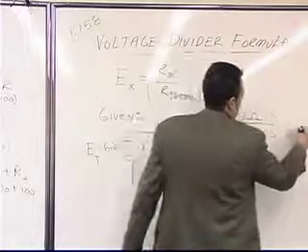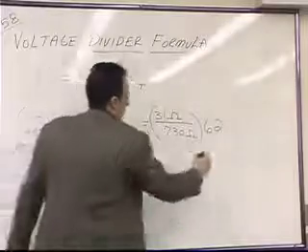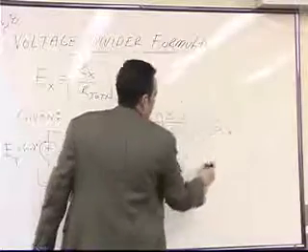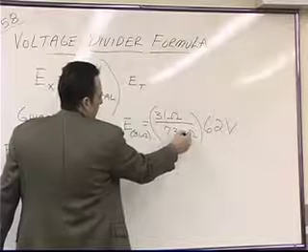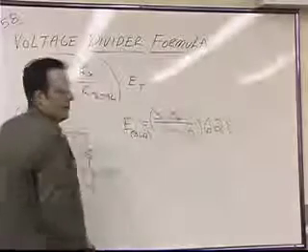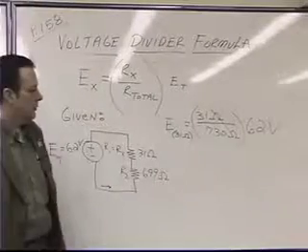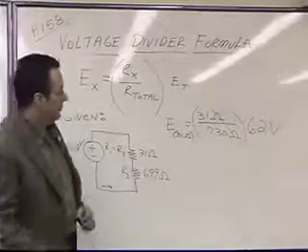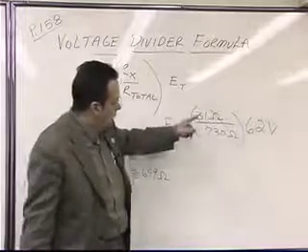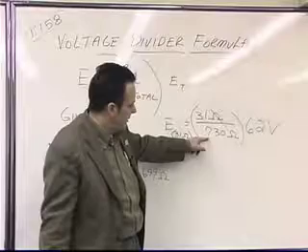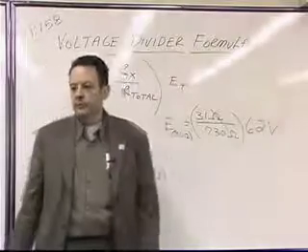62, which is the source voltage. And what is the unit on the 62? Volts. And what happens to the unit of ohms? They cancel out. Because remember, anything over itself is 1. Okay? So now, get your calculators out and go 31 divided by 730 times 62 equals? 2.632.